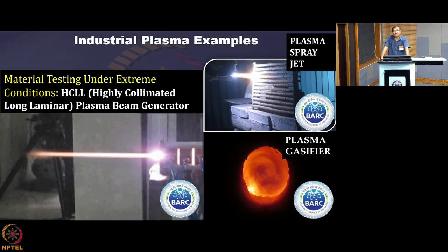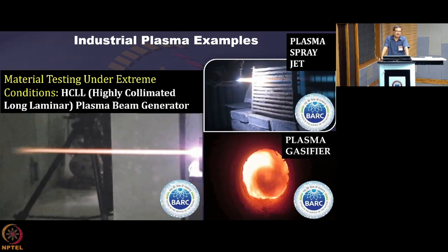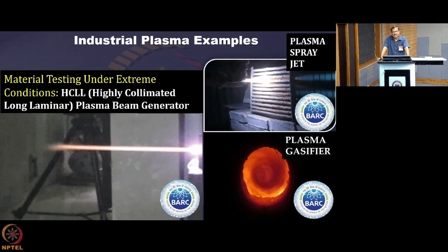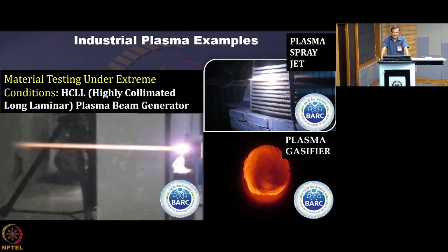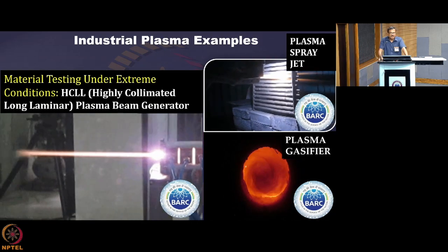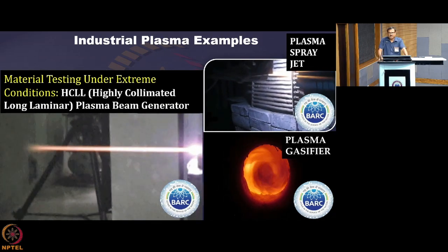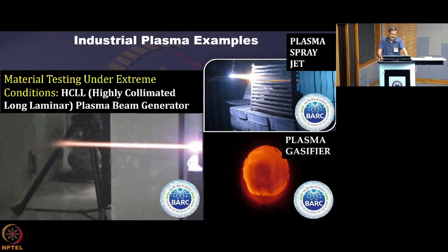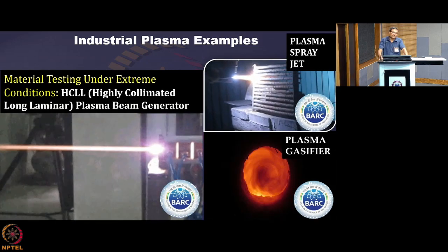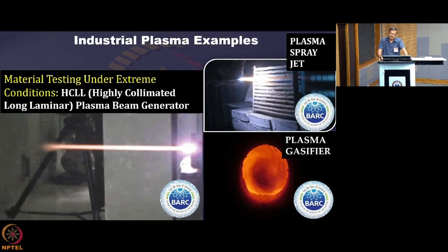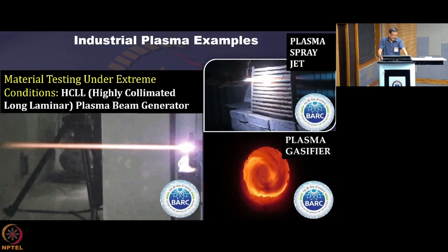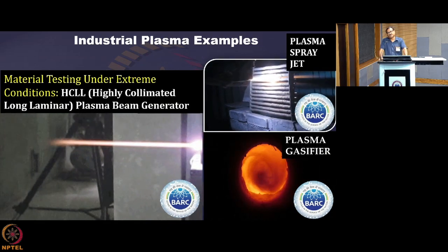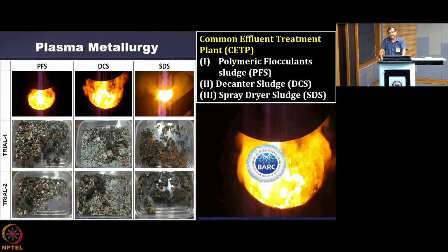But if we want to melt such high melting point material, the conventional technique doesn't work. For example, resistive heating can reach a high temperature, but it will not be able to instantaneously melt that material and coat the object. So plasma becomes a very useful technique for that.